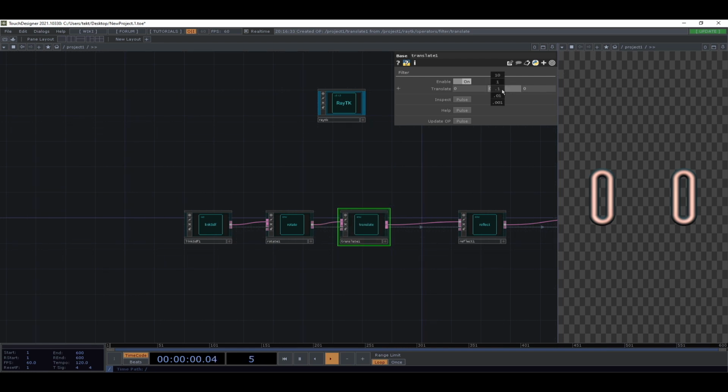All right, so if you're changing the X, then because that's the axis that you're mirroring over, it'll move in the opposite direction on the other side. But if you change the Y or the Z, it's going to do the same thing on both sides. And you don't really have any control over it beyond that.